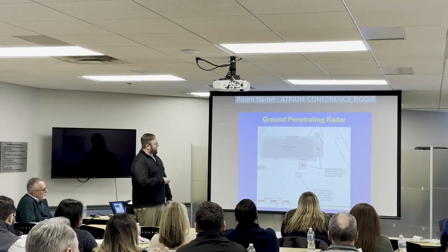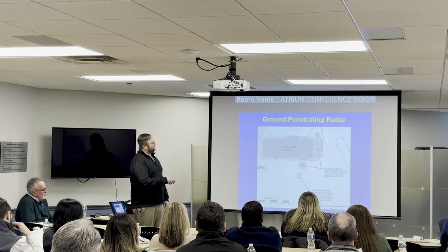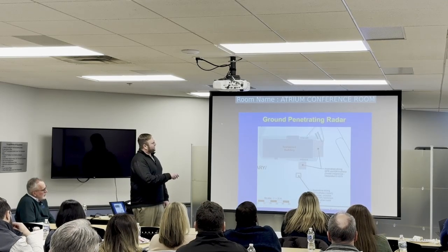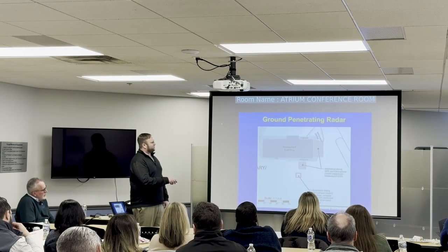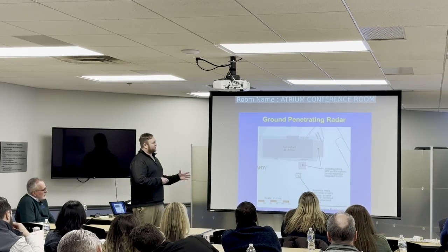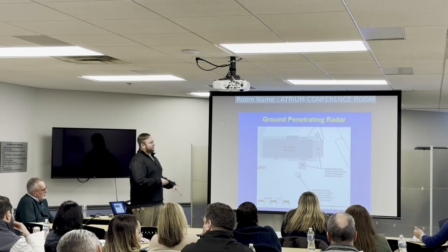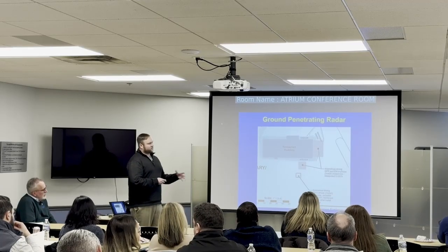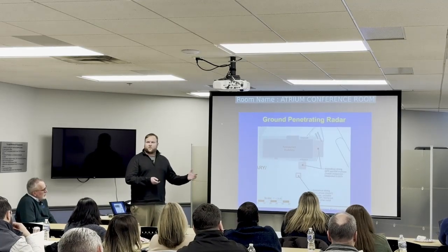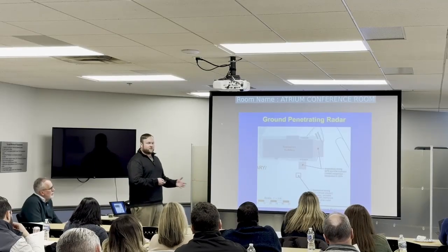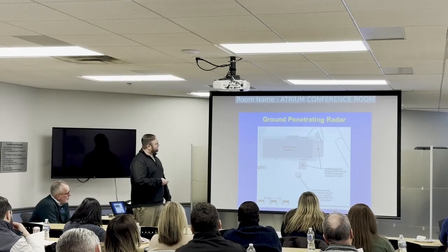Here's an example of where we scanned GPR near a restaurant building. We located some objects with signatures that were consistent with a tank in the ground. Unfortunately, in this scenario, they were partially beneath the building. But this is a tool we'll use at the site to determine if tanks still remain or to determine prior excavation areas.